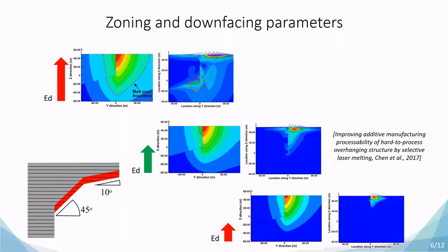But also we're going to have a fluid flow which is dripping on the previously printed part, therefore increasing the surface roughness of the product, and also decreasing again the geometrical accuracy. On the other side, if we use an energy density which is too low, we can say that we are within the geometrical accuracy of the part, at least in the Z direction.